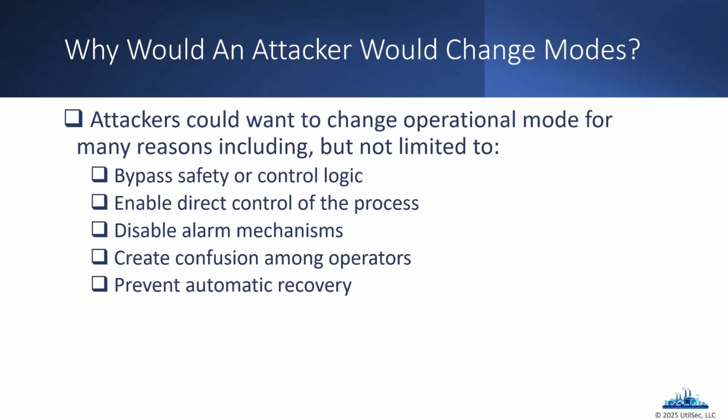But there's a reason that there are 3 different techniques related to the operational mode or the operating mode on controllers. There's 3 of those different techniques listed in MITRE ATT&CK. Because attackers, once they're in the environment, want to find out what operating mode that PLC is in. But then they also want to have the ability to change that operating mode. And why?